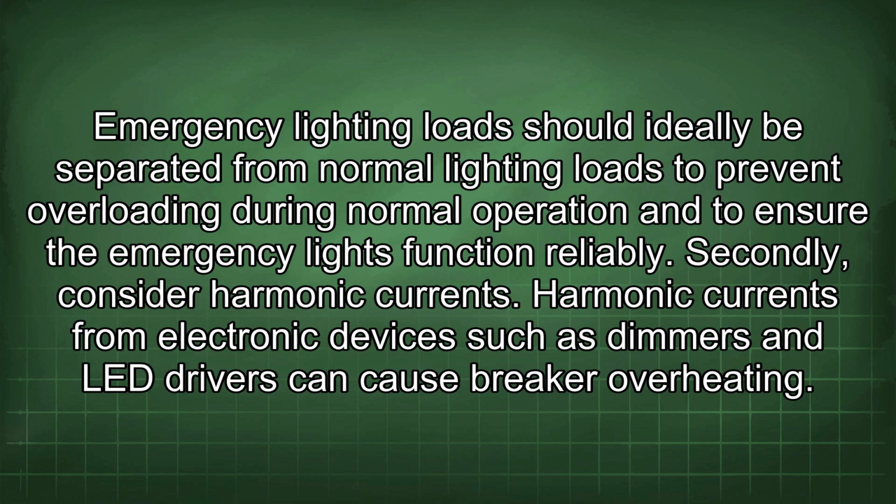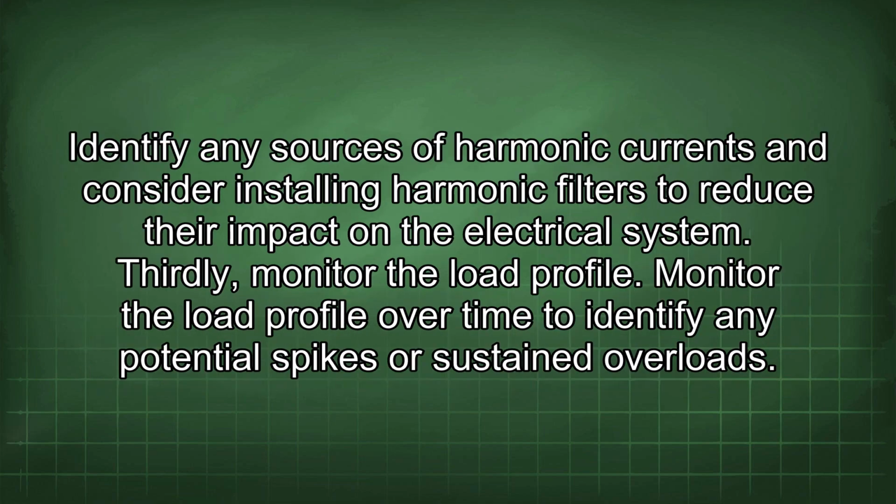Secondly, consider harmonic currents. Harmonic currents from electronic devices such as dimmers and LED drivers can cause breaker overheating. Identify any sources of harmonic currents and consider installing harmonic filters to reduce their impact on the electrical system.